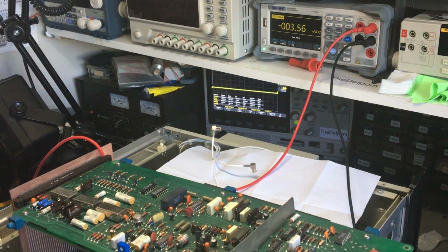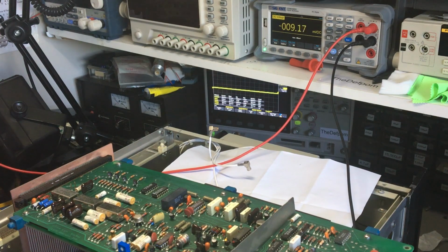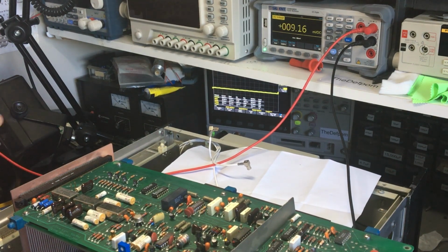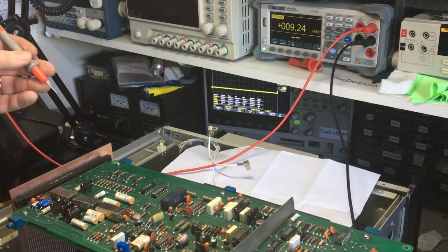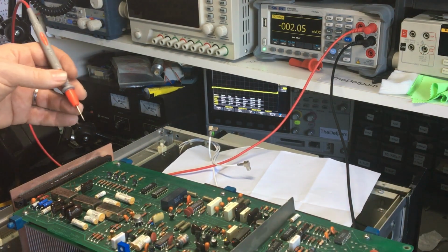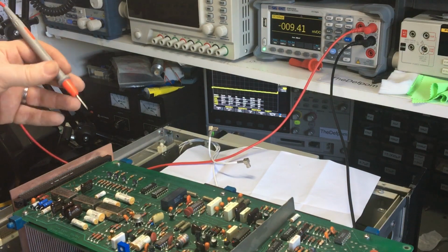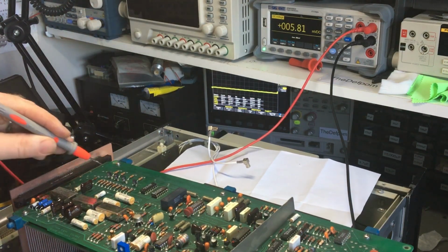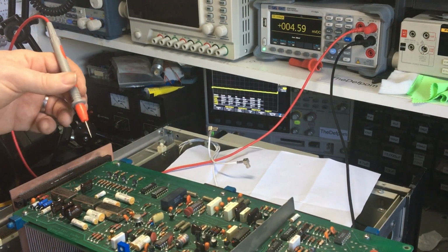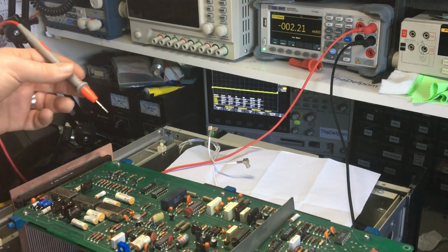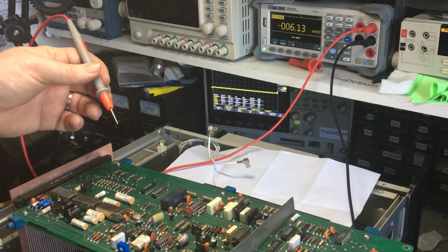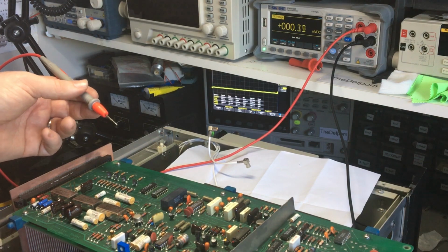Now I need to figure out what next test I'm going to do. Right, it's going to be a little bit noisier now because I've turned the air conditioning on because it's a bit hot in here. So, I'm doing voltage checks on the switching transistors, just to verify that they are all switching as they should be, because it's not just the relays which operate, it's also the switching transistors.